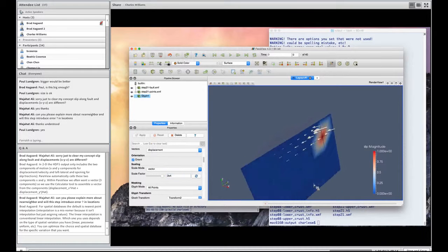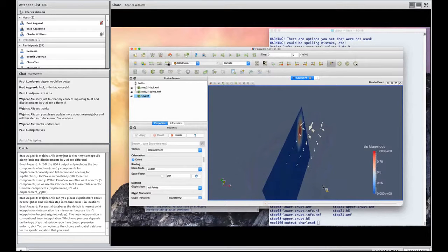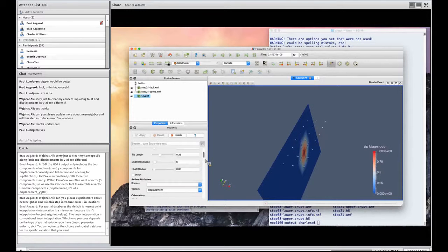Okay. So now again, you can see on the fault is your applied impulse, and these vectors are showing the surface response due to that impulse. So this is a left lateral impulse, and then we can just go through and see what they do. That's a reverse impulse, and they're alternating back and forth here. So you can go through and see what all the different ones do. So this would be your Green's functions generated for 3D.